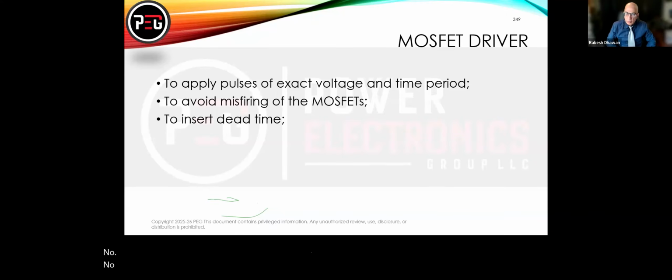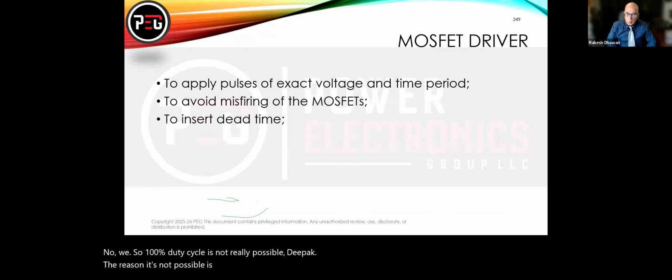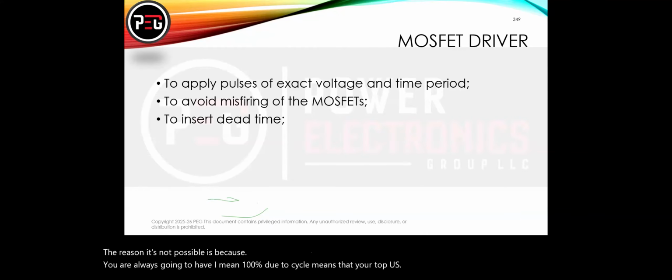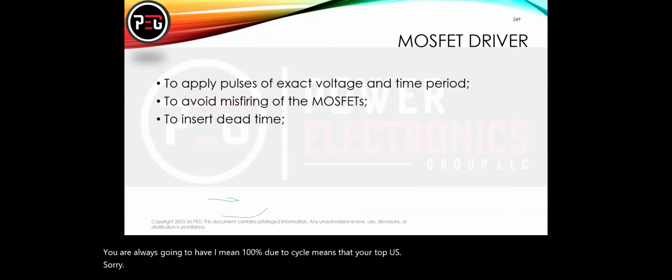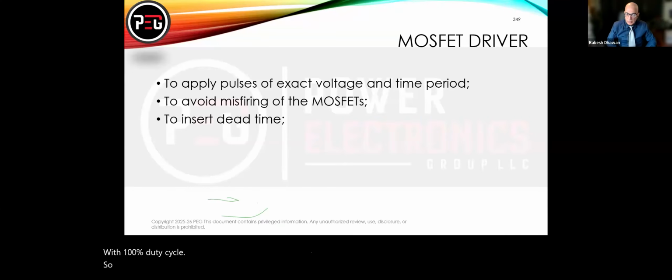So 100% duty cycle is not really possible, people. The reason is that 100% duty cycle means your top dead band has to also be there. Yes, that band has to be there, and you cannot modulate your voltage with 100% duty cycle. So you always have to have some kind of dead band, which also helps to charge your bootstrap. But that's a good question.